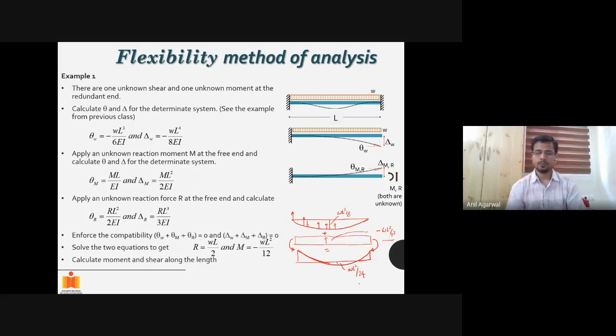Fine. You can understand this concept even further. Let's say I don't have a full fixity. If I don't have a full fixity, I have a spring here, let's say. I'm kind of digressing here, but that's also an important discussion. It should be discussed more rigorously in design courses, but we usually don't get so much time in a design course. I was hoping to get full fixity at both ends, but somehow I didn't get that for whatever reason.